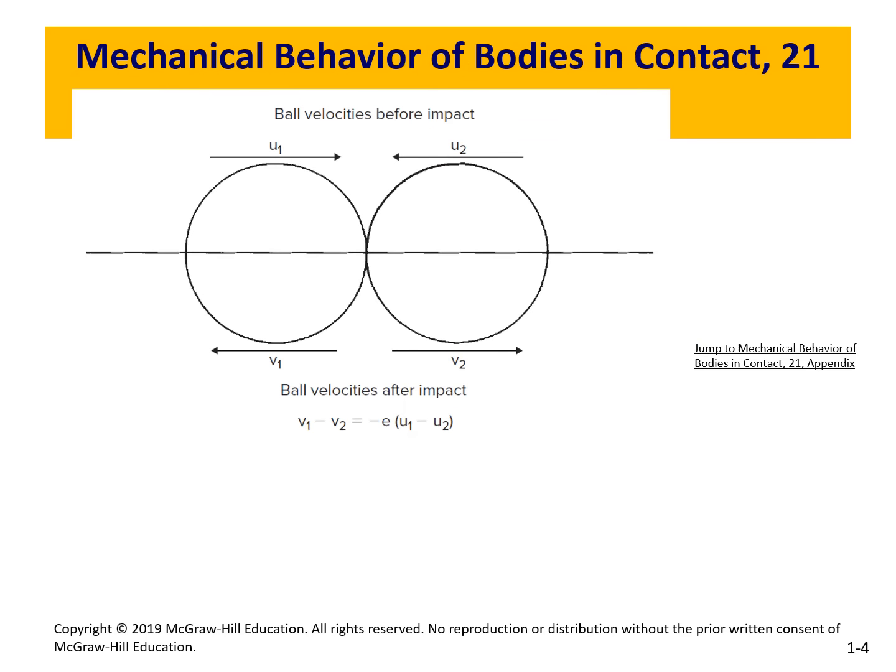Now, if you look at the schematic here, you can see that we have two balls. They're colliding. U's are the velocities before. So U1 is the velocity of the left ball going to the right, and U2 to the left. And make sure that this is velocity, which means that we have vectors, right? One of them should be positive and the other should be negative. And then you have the velocities after the impact, V1 and V2. So V1 minus V2 equals minus (U1 minus U2). And that's how you measure E, which is the coefficient of restitution.